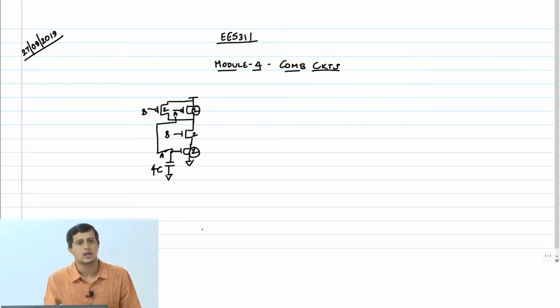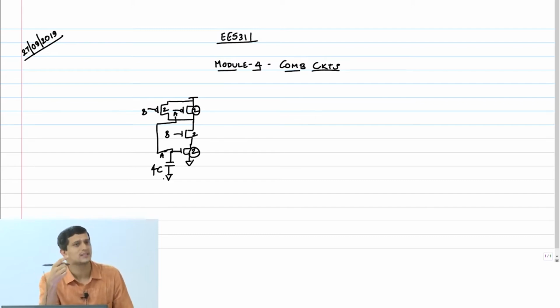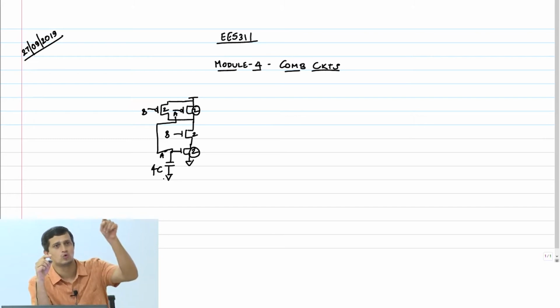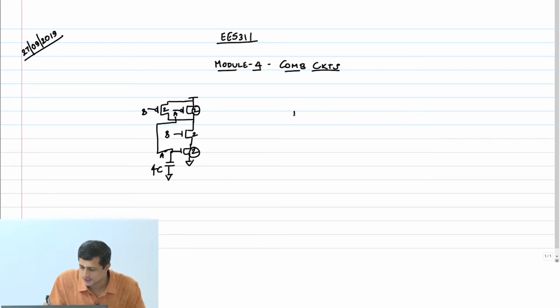Right, and logical effort is defined as the ratio of input gate capacitance to the gate capacitance of a static CMOS inverter with identical drive strength. Okay, so because we have sized the NAND gate already to have 2, 2, 2, 2, wherein we have made sure that the resistances are the same already, our reference inverter here is just going to be the standard reference CMOS inverter, which is going to be 1, 2.